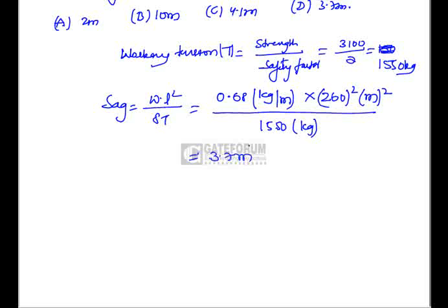Be careful with units because he has given conductor weight as 680 kg per kilometer and length of span as 260 meters. Okay, be careful about units, and the answer you will get is 3.7 meters, that is option D.